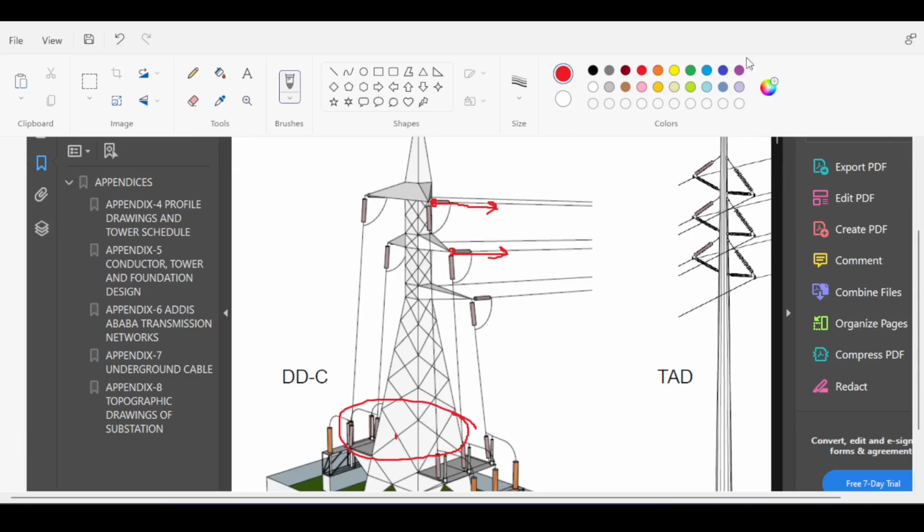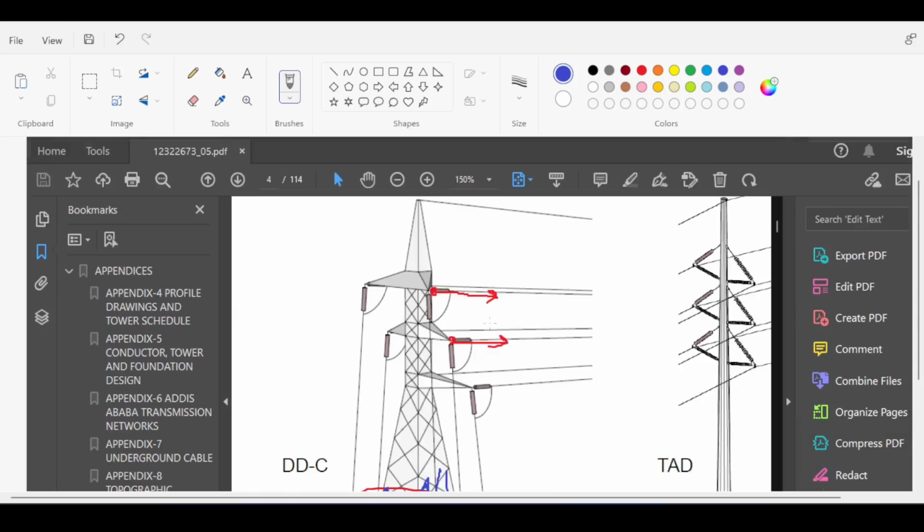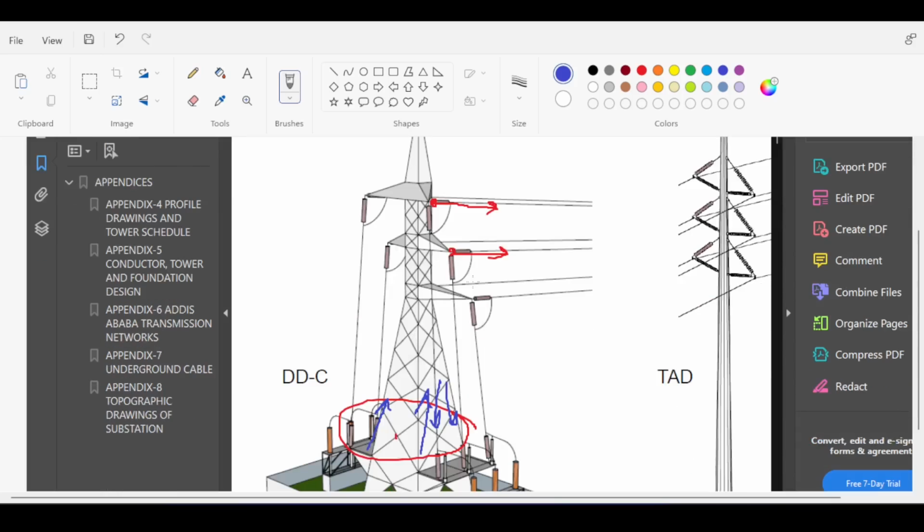And now this is a truss, so moments are not carried by members. However, you will have huge tension forces on those truss members and compression forces on those truss members. So this is a little bit dangerous and you need to take a better look at those. And that's why sometimes you will see in real life some anchoring points where you anchor your entire structure. This is sometimes happening, that you have anchoring points for the structure to counteract the tension forces and relieve the structure from carrying all those tension forces themselves by helping it with anchors and cables to anchor them.